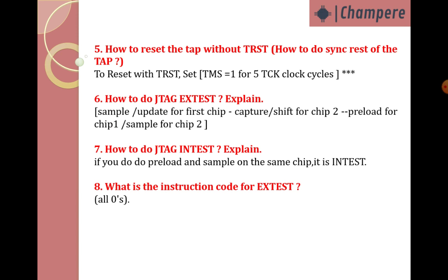How does JTAG INTEST work? If you do preload and sample on the same chip, it is INTEST. If you do the same thing, preload and sample, it comes under INTEST. What is the instruction code for EXTEST? The instruction code is all zeros, all input pins will be 0. That is EXTEST.